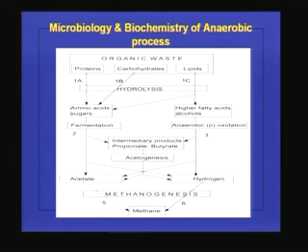But the acidogens and fermentative bacteria, some of them are facultative type bacteria. So if some oxygen is present in the system, they will be able to remove that oxygen by oxidative phosphorylation, and the system will be converted to a complete anaerobic process. So that is the pathway I have shown earlier. So now this one will be much more clear.